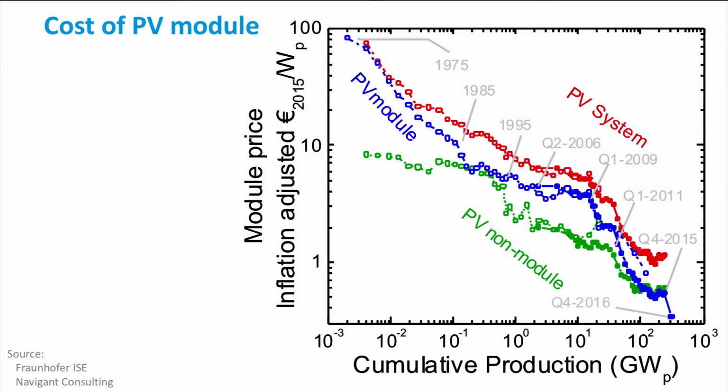This shows the advantage of crystalline silicon PV technology with respect to thin film technologies. Crystalline silicon modules have efficiencies ranging from 14% up to 20%. Higher conversion efficiencies means higher yields per area. While the non-modular costs per area are the same, the cost price per watt peak of the non-modular cost will consequently be lower for modules with higher conversion efficiencies.